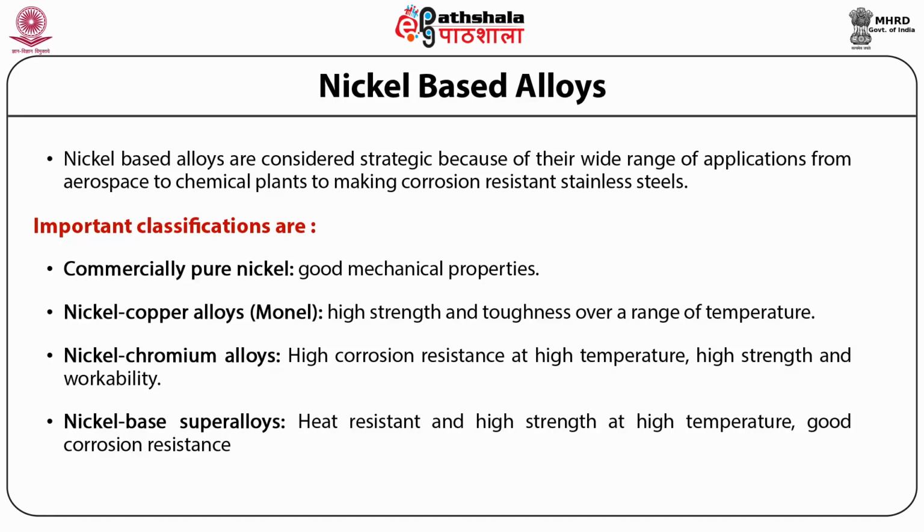Major application fields are aircrafts, space wheels, rocket engines, industrial gas turbines, high temperature applications, nuclear reactors, submarines, steam power plants, petrochemical equipment, etc. Iron is added to replace some of nickel as it has lower cost in case of nickel iron superalloys. Therefore, it is used at lower temperatures.